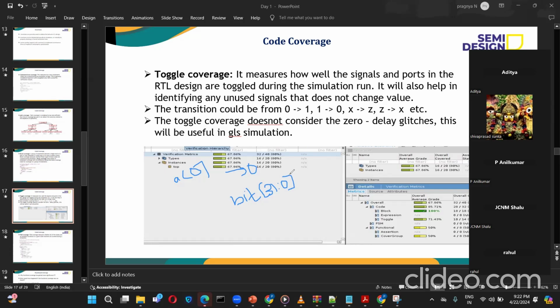See, there could be a reason, and it will directly show us. For example, 32-bit data is not toggling. That is because maybe we are considering some aligned address or something. In that case, we can write a reason that only the lower bits are not used. We can understand from the design why these bits are not covered.